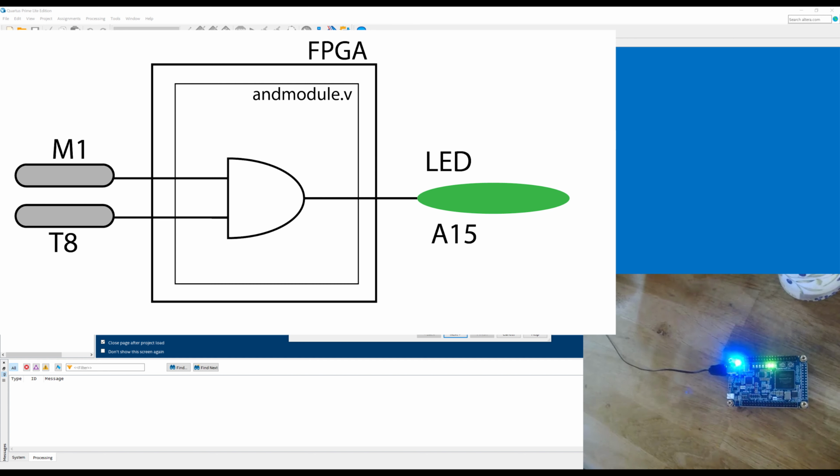Now, this is the easiest way to program, but it's not really the most powerful. We'll come to learn other ways of programming in Verilog, especially the behavioral paradigm, which is much more powerful because you can actually describe the function of your design rather than the design itself. Because at the gate level, you just instantiate the design gate by gate. But of course, as your design becomes more complex, you could end up with hundreds or thousands of logic gates, and then it becomes very difficult to do that manually.